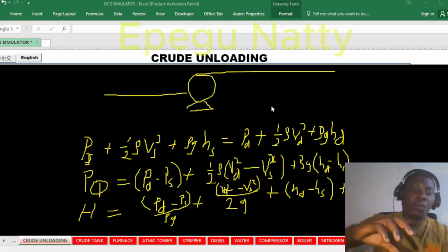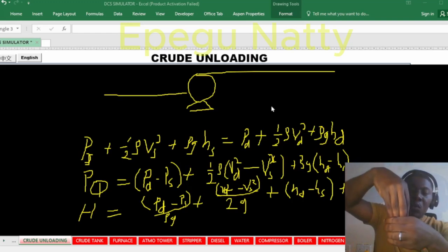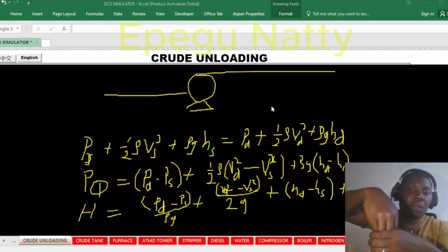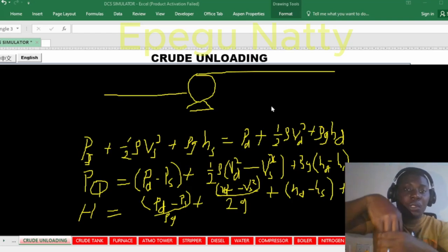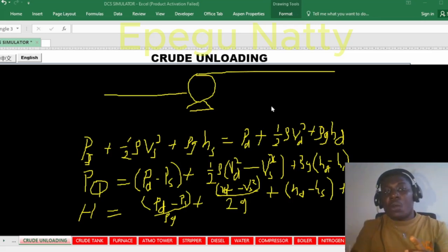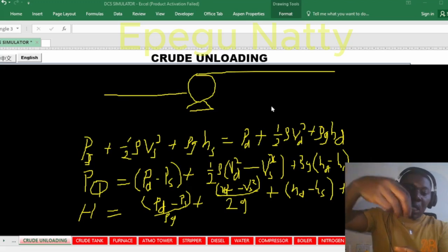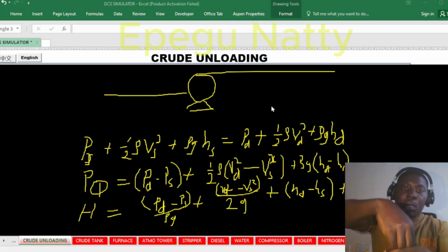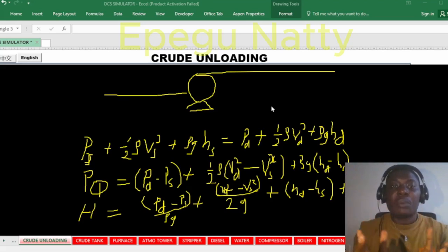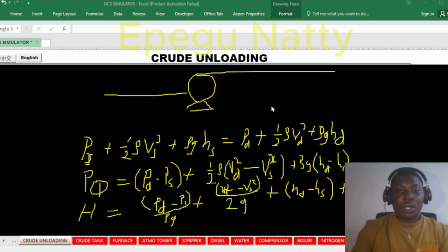Don't forget, when you try to close a valve, something goes into the pipe to prevent a flow. That is a head loss. Now that loss is what is reducing the flow rate on that line. What the valve closure does is, there is a ball that goes into the pipeline to block the flow. It's called a trim. Now the assembly of the valve, where it actually functions in the closure and opening of the control valve, is called a trim. We are going to look at the trim very soon.